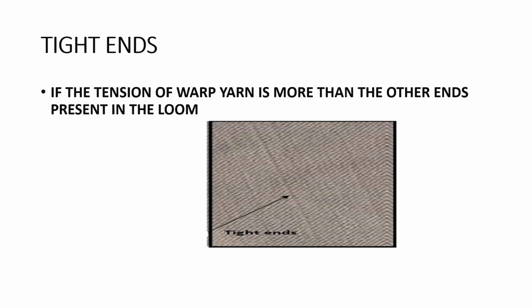That is the reason normally during analysis of the defects, people cut that area, total warp wise or weft wise, and try to understand how this defect has come. Whether the defect has come from processing, or due to yarn thickness or yarn twist, whatever it may be.